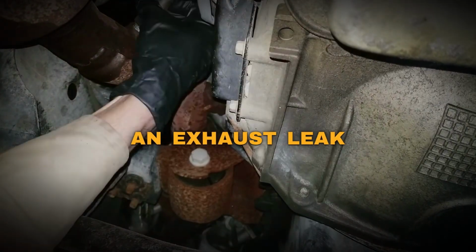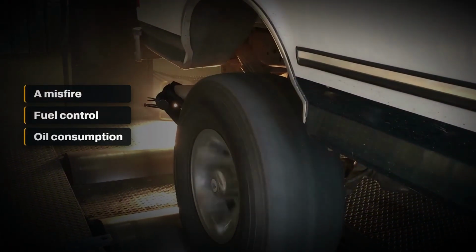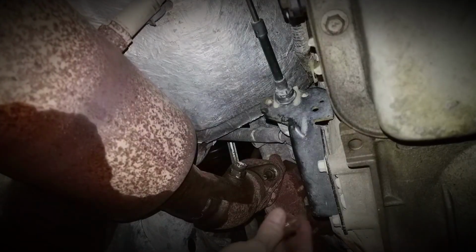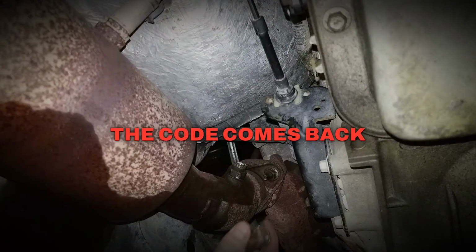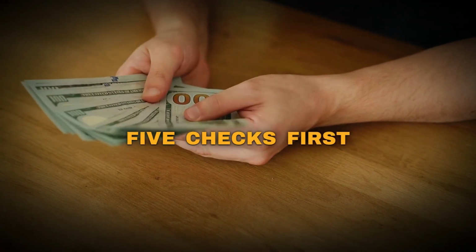An exhaust leak can affect the sensor readings. A misfire, fuel control problem, oil consumption, or coolant leak can damage the converter. Replacing the converter without finding the cause can bring the same code back. Before approving an expensive repair, make these 5 checks.